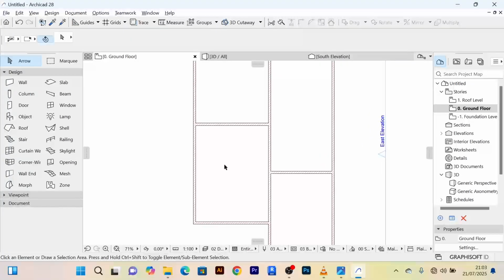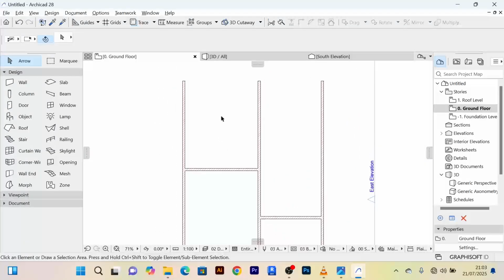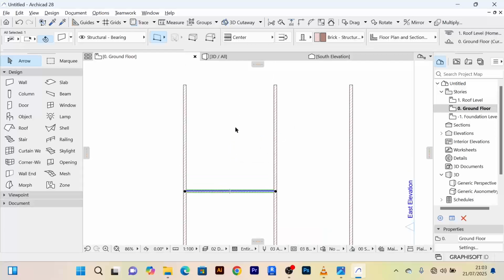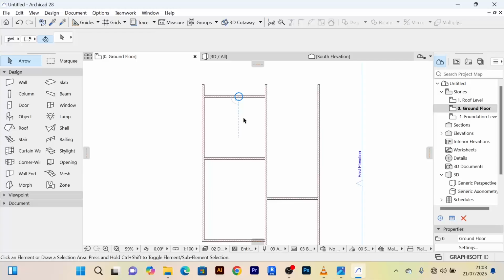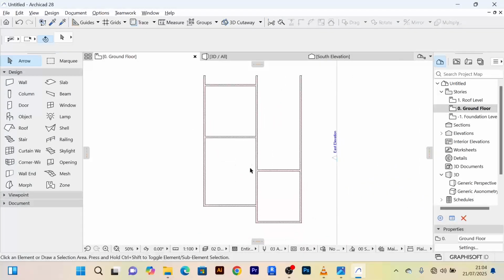And then I'll need, this is our living room. We shall need the kitchen and the dining. So I'll move this inside. I'll just Control Shift and D again to drag this. I'll say I'm dragging at 6 meters, that is 6.2. Just like that, I have myself 6 meters here. I'll deselect all. So now this part will have both the kitchen, let me escape, it will have both the kitchen and the dining, and this is the living room.